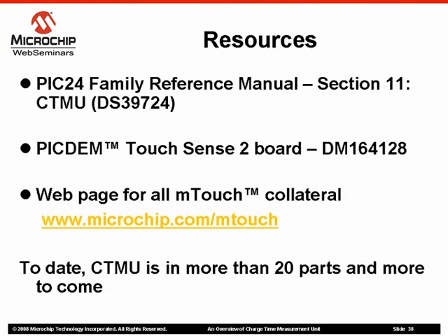There are many resources available from Microchip for CTMU and capacitive touch sensing application. First, refer to the family reference manual. The number here is DS39724. Second is a demo board called the PICDEM TouchSense 2 demo board, which demonstrates CTMU in capacitive touch sensing application. Third is visit www.microchip.com/mtouch for update and all related collateral. There are more than 20 PIC microcontrollers with CTMU and many more are following.